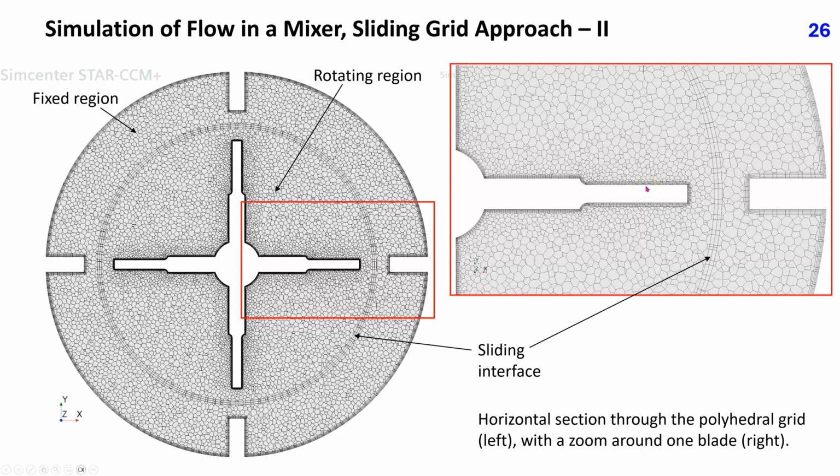The flow is assumed to be laminar because the fluid is very viscous and the rotation rate is relatively low. Different arrangements may be required for turbulent flows. This will be addressed in lecture 32. The grid is locally refined near impeller walls because higher gradients are expected there.